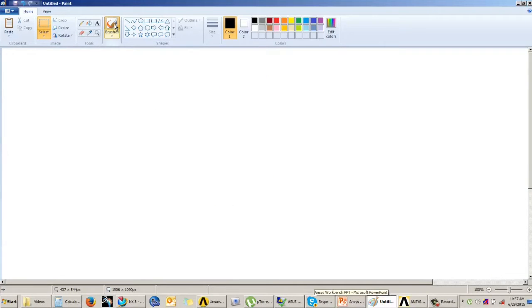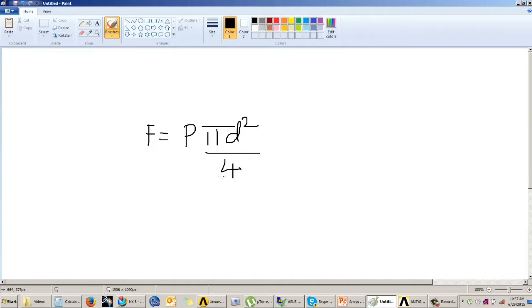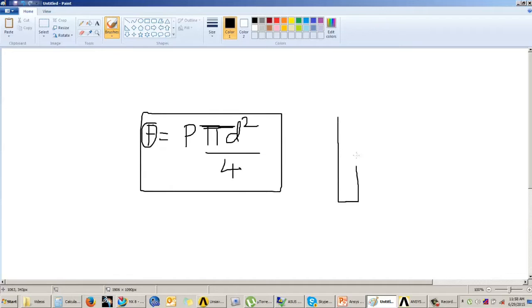Because it is going to be closed from both the sides, we will have to apply a force, and we will calculate this force based on the pressure and the area of the circle. So this is the formula to calculate this force, which will actually act on the pressure vessel from the top, just to create the closed section condition.